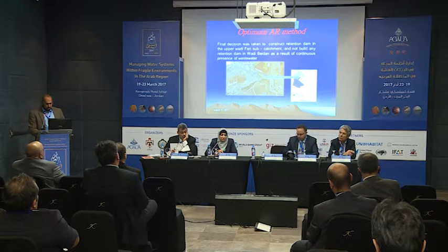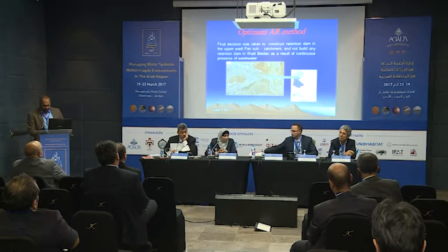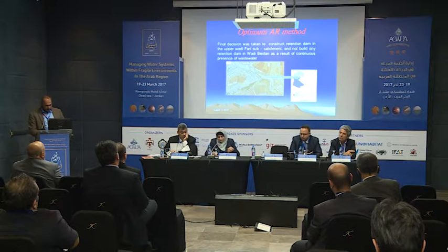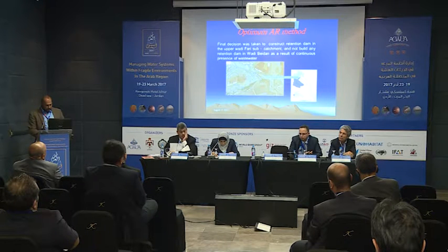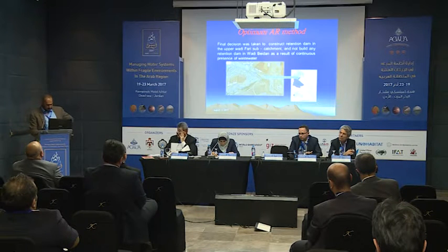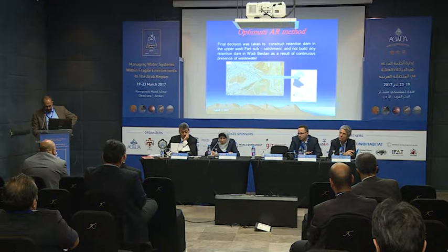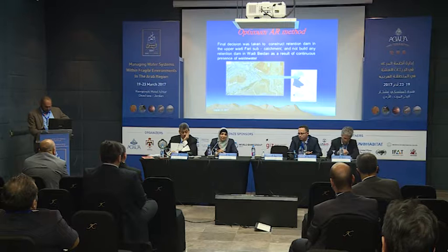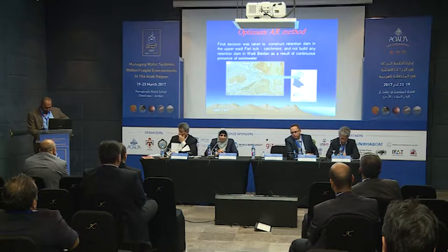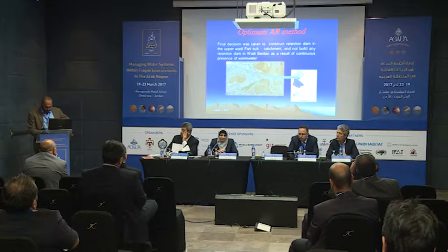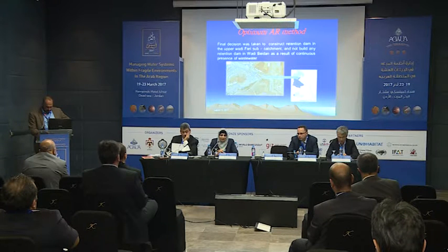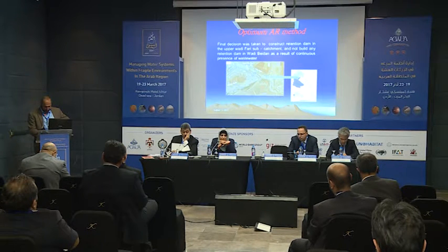The final decision was taken to construct a retention dam in the upper Wadi Faria subcatchment and not to build retention in the other branch, Wadi Badan, because of the continuous presence of wastewater in Wadi Badan. So we are now working in the last branch of Faria catchment, which is the sub-catchment Faria. This picture shows exactly the location of the retention dam, according to the main wadis of the two branches.